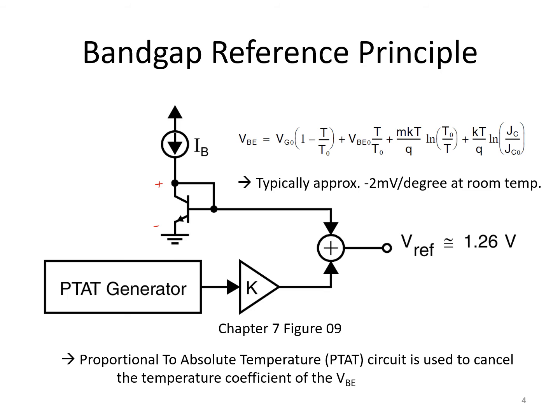So you can, in any case, push a current through a forward biased PN junction and thereby develop this forward voltage drop. We'll call it VBE, the base emitter drop, assuming that the PN structure is a bipolar transistor, but in any case, it can even be just a simple PN junction. Regardless, let's label that forward voltage drop VBE.